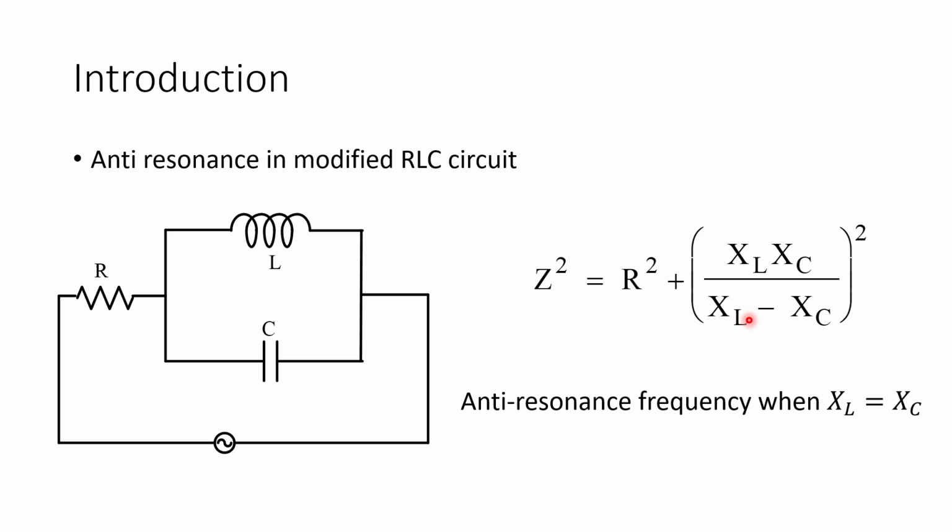And again, you would get the exact same number by using the same L and C. So the frequency for anti-resonance would be 1 over 2 pi square root of L and C. So there you could actually have the circuit where, if you tune it to the anti-resonant frequency, most or no power at all would go into R, but most, if not all, power would go into L and C. So R would get no energy in this case.